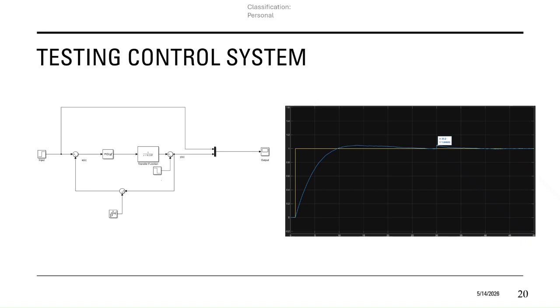So as you can see here, I've given in a unit impulse added after the transfer function. U of t is going to give me a unit impulse at t equals 30 seconds. And this is in the feedback loop, a noise disturbance. Within the PID controller itself, I have added a limit from 0 to 25 so that I may see how the system compares when it reaches the max volume. What does it do? Does it fail or does it not?